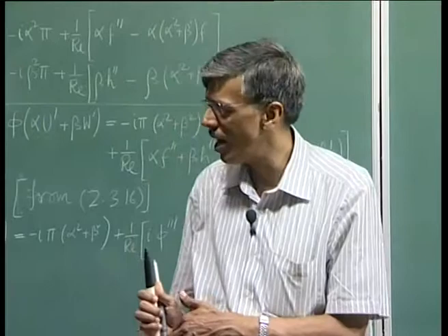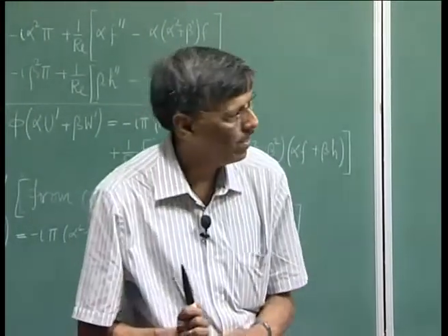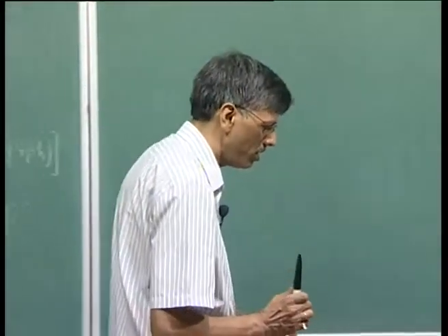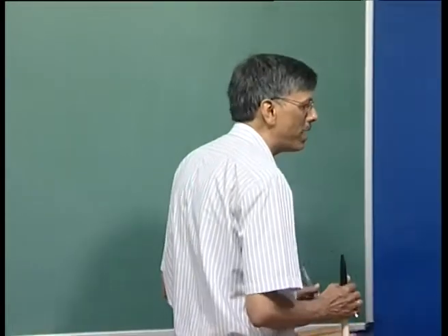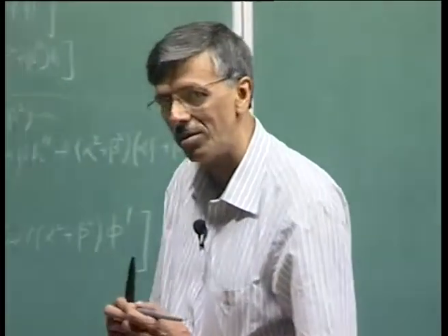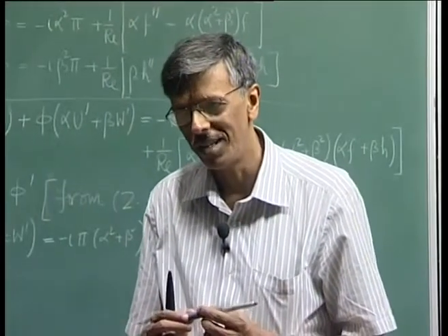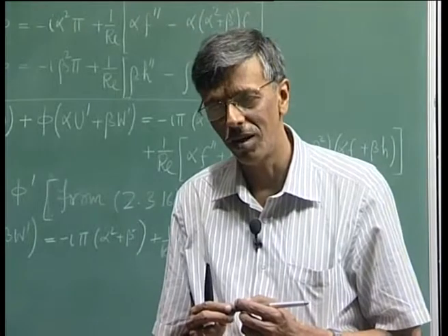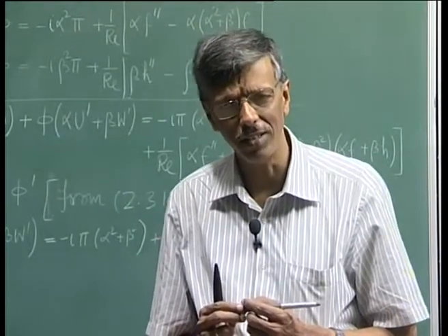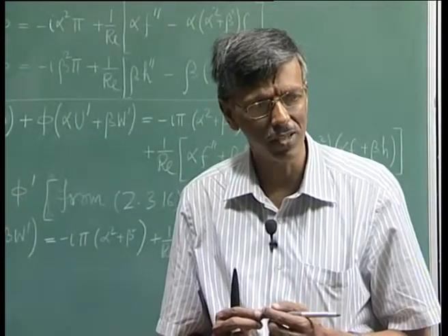Squire's theorem very clearly identifies that it would be better to study the 2-dimensional field, as it will give you the more conservative estimate. This also brings to your mind what we talked about in terms of Kelvin-Helmholtz instability. There we found the disturbances were essentially 2D, right. The group velocity in the other direction was 0.